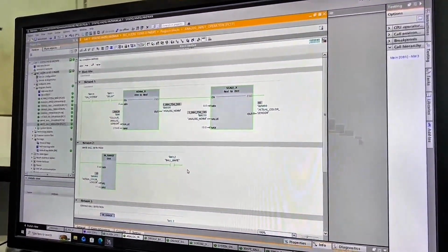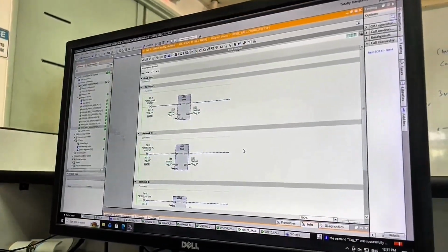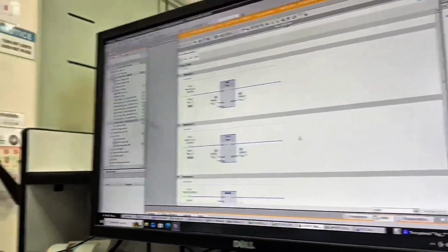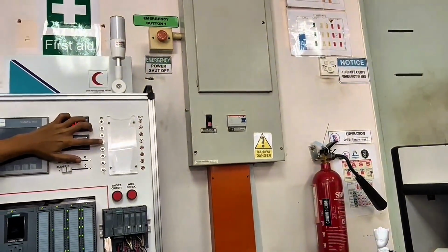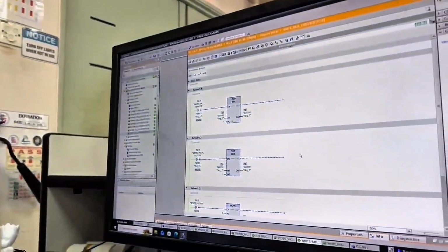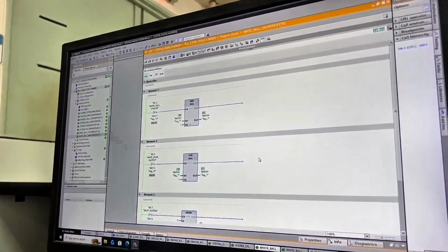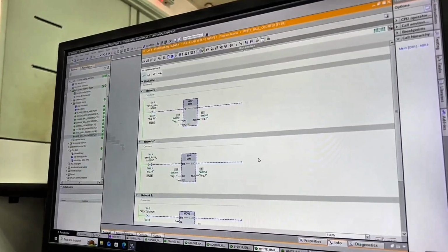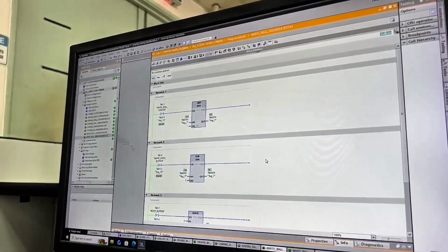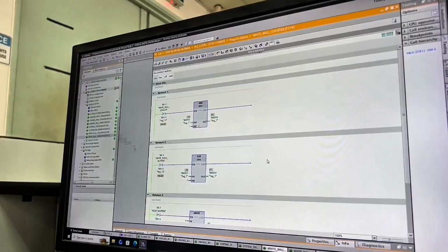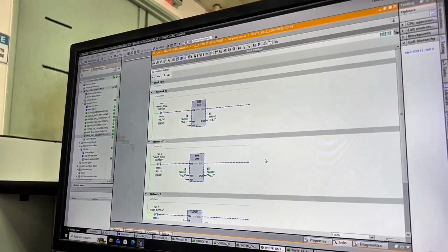The slider needs to be moved slightly further to activate the analog ball sensor for the orange ball, which will open the corresponding contact. For the next operation, which is the white ball counter, in network 1, press toggle 3, white ball sensor at PLC input I0.3, to add 1 count for a white ball. In network 2, press toggle 4 to subtract 3 white balls from the counter.